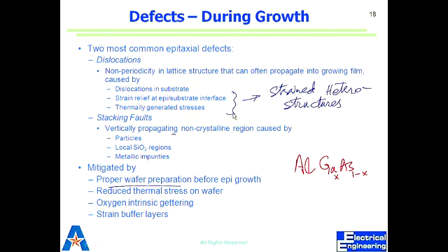So these are what are used in an area called strained heterostructures, where I think one of you talked about it later, but where we deliberately make them in stress to increase mobility, but we don't want to get dislocations. So what we do is we make graded junctions. We have the quantities change over height, right? So as you go away from the interface, you get to change X and get to your material that you want.